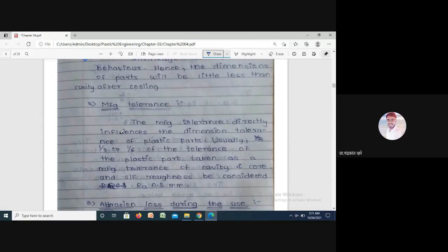Suppose your shaft is 50 mm diameter, then you need to manufacture the shaft on the lathe machine as 50 plus 0.5 mm. After this lathe operation, you need to finish the shaft, in this case by polishing. For the polishing operation, you need to give 0.5 mm, for smoothness and finishing purposes.